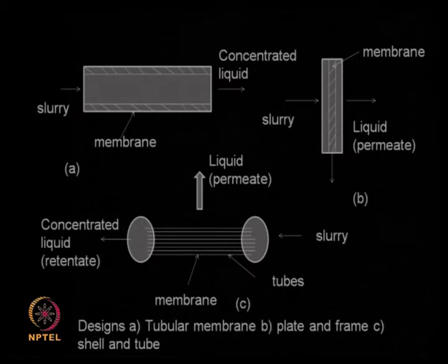So this is another design. If you want to replace a tube, you need to open up this heat exchanger pipe, take one of these tubes which might have been fouled beyond use or might have been physically, mechanically damaged, then you can put another tube here and carry out your job. So that is another way of looking at this shell and tube type of design actually.